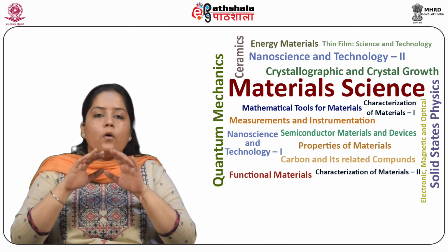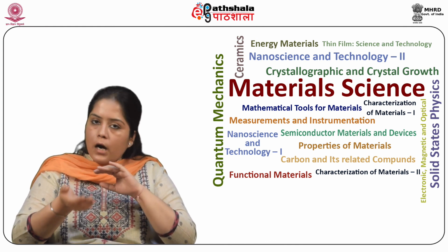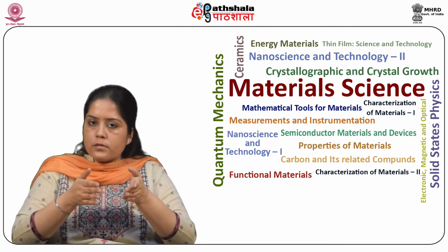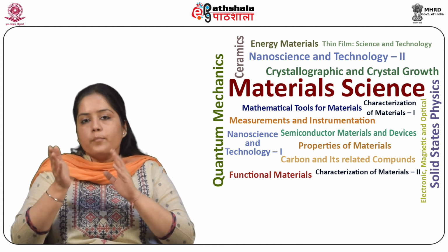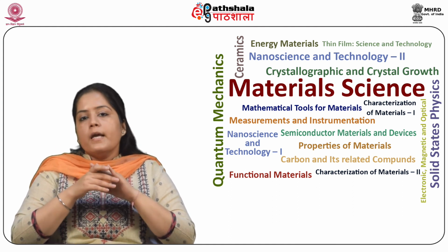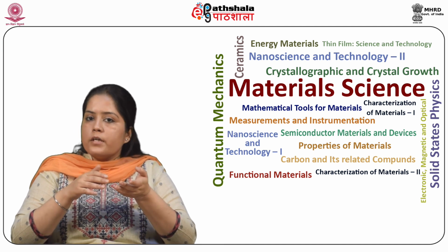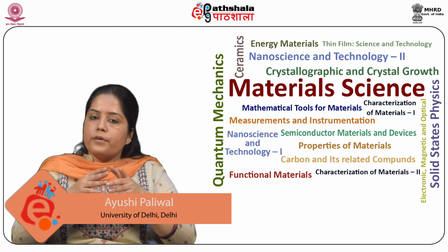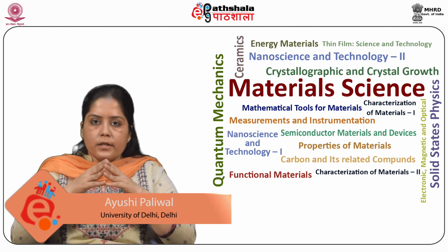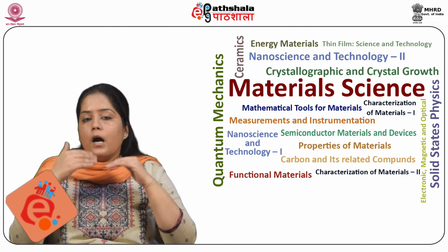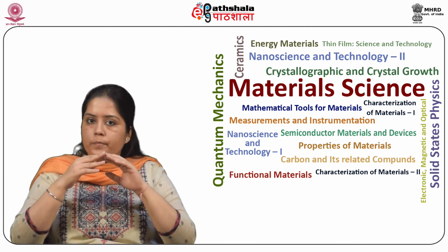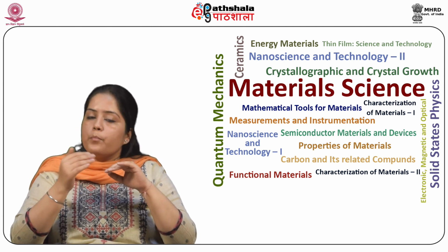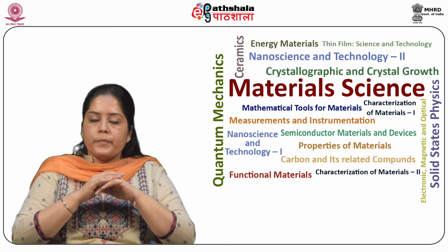Third, on the other hand, hard magnetic materials are basically alnicos or rare earth based magnets, essentially neodymium or samarium based, the latter offering high magnetic remanence as well as a higher BH value exceeding 100 kilojoules per meter cube. Thank you.